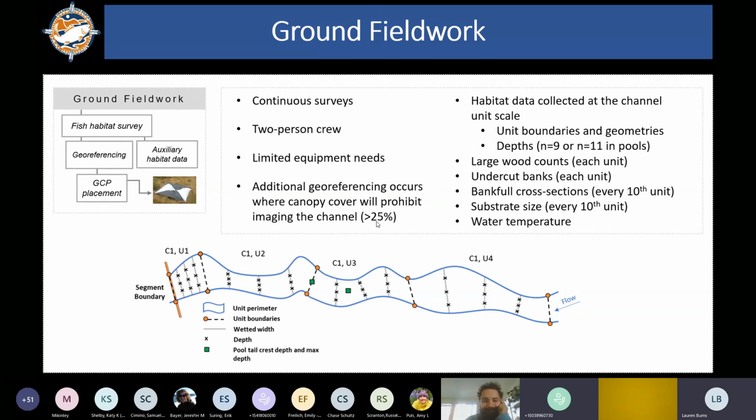Flashlights. Yeah, don't have shadows. Try everything to not have shadows in the imagery. Collect at solar noon. You mentioned that, Lauren, in yours, that's just a basic protocol. Well, our typical rule of thumb is trying to collect at 2 hours on either end of solar noon. And solar noon is something you can find when it's not always at like 12 p.m. Sometimes it's at like 3 o'clock or 1 o'clock.